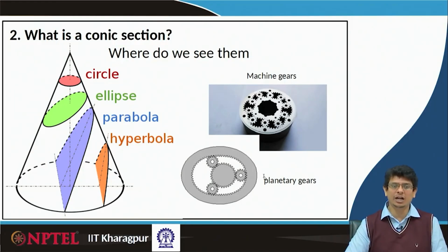For example, if we take your mini drafter, one part of the mini drafter is fixed on one side, and once you tighten the scale, wherever you move this mechanical drafter, it always constructs vertical and horizontal lines. For that purpose we use a 4-bar mechanism to construct these vertical and horizontal lines.